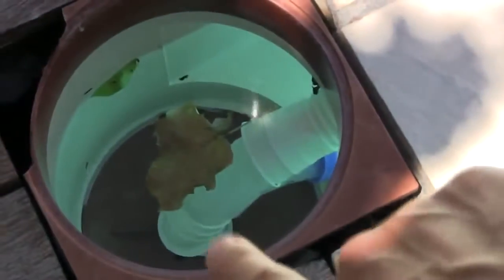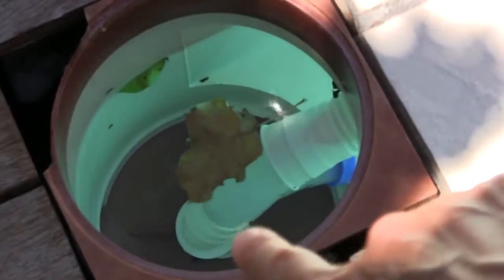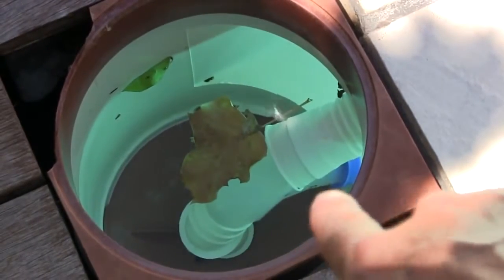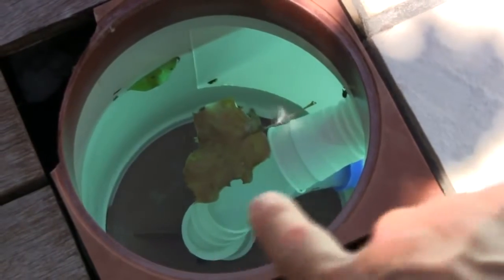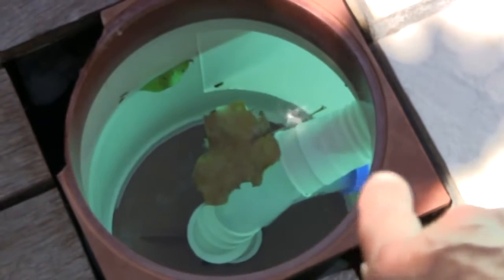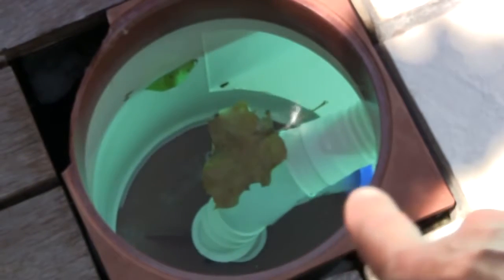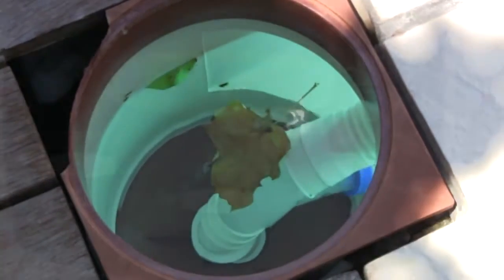So here we go in my weir. This is obviously where the pump is pulling through into the catchment basket. And on this little adapter over here, you can see there's a little blue item, and that's where there's a spring where you can adjust the suction pressure. And by playing with the tension on that spring, I was able to adjust this so it runs at very low pressure from the pump itself.